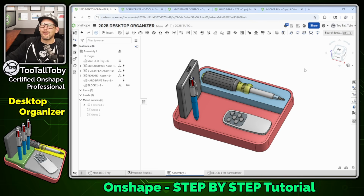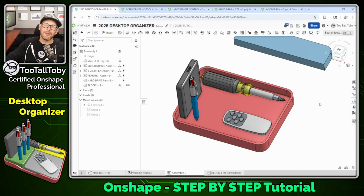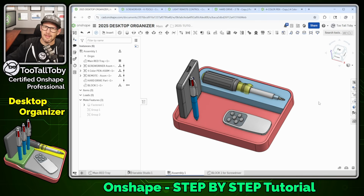So we're going to take that block 1 and we're going to add that to the assembly, and there we go. And so now what we can do is we can take this block here, and you'll notice that it can just be dragged off into space. That's really not what we want with this in-context part. So let's press Control Z to undo that, and then let's press the S key and do a group.